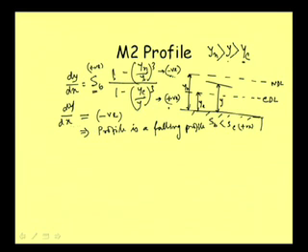So depth y is falling with respect to x, it is decreasing with respect to x. In the direction x, meaning the direction of flow definitely, with the direction of flow the depth is decreasing, and that is why I can now draw this profile more confidently, that it is like this. Up to that much it is all right, that it is a falling profile, that is one characteristic we are getting of the M2 profile.